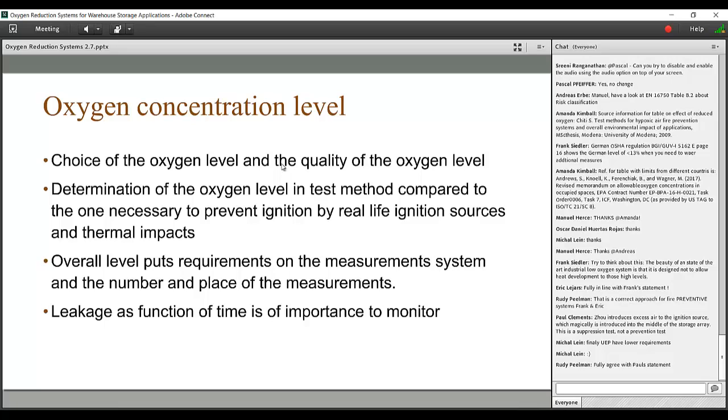And throughout the life of the building, this means that you need to have good controls on understanding what the actual oxygen concentration is in the protected space over time, and understanding whether you have permeability of the enclosure compartments, how often are doors open and closed, are you taking into account doors open for movement back and forth of goods, do you have issues with aging of the containment of the facility, and so forth.